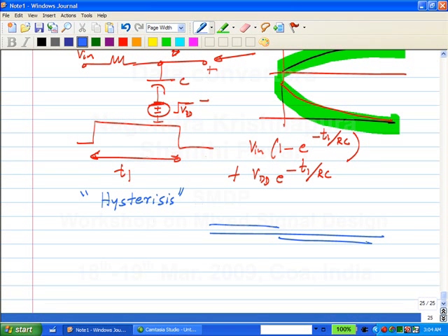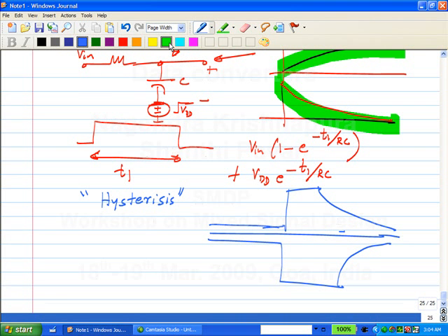The input in the first comparison was just above 0, so the decision made would be on the two capacitors, the voltages would be like this, and then these have not decayed fast enough. And you are attempting to charge this to a small difference in the opposite direction. So the VDD, which is not yet decayed, will simply overwhelm the small negative input.